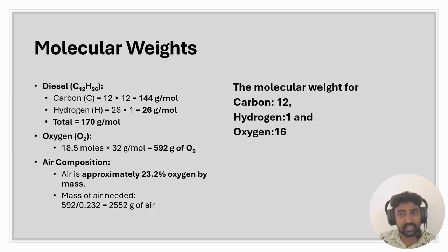So there is far more air in the cylinder than the stoichiometric amount needed for the injected fuel. Is it clear? This is the answer to why always lean in diesel.